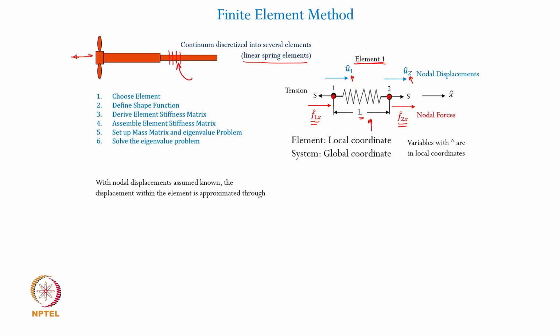Now, with these nodal displacements known at the node locations, make a note here that this u1 cap and u2 cap pertain to the displacements of the nodes of the element. If I want to know the behavior or the displacement within the element, I should have a function that defines the displacements within the element.